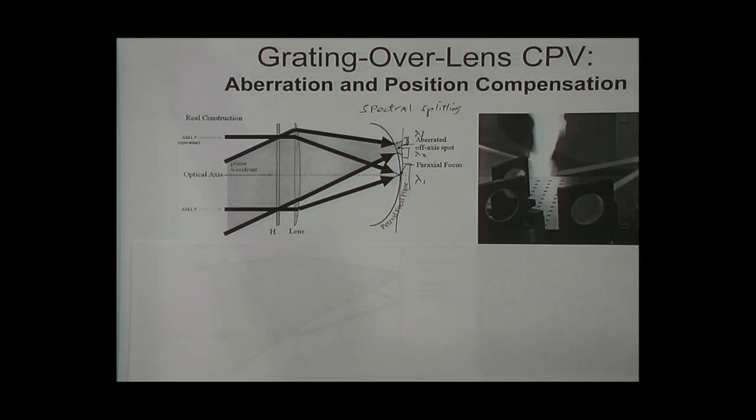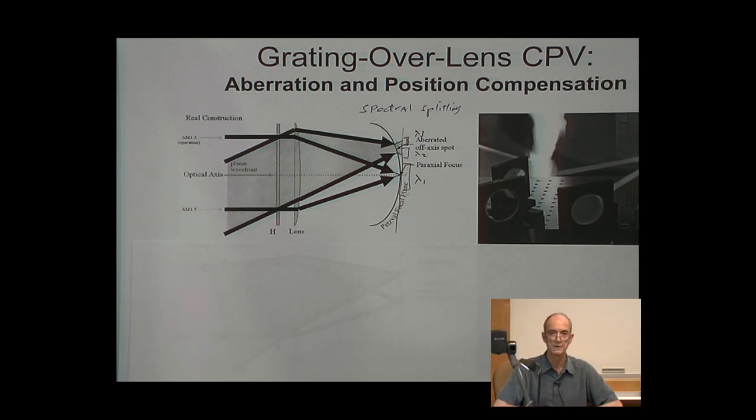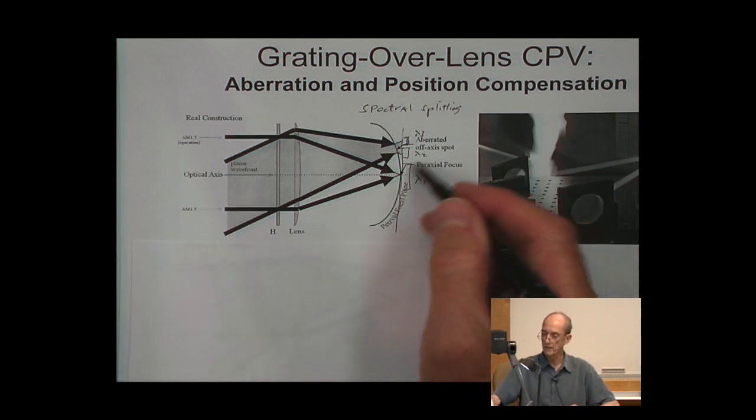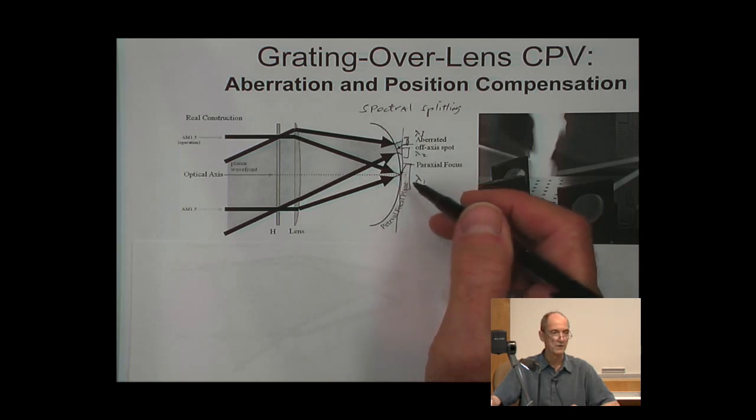There's a very famous paper written in 1961 by Shockley and Queisser. Bill Shockley, Nobel Prize winner for inventing the transistor, and Queisser, formulated this. They did this analysis of this problem and found with a single bandgap cell you can only get 33%. But if you have multiple junctions, then you can capture more of that illumination.